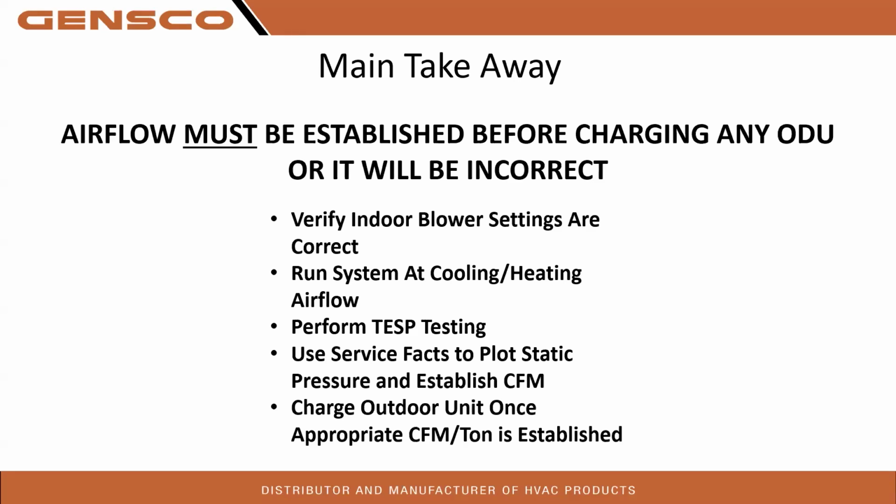Even if you use a true flow plate, that is great. Still need that information, right? A true flow plate does not give you an excuse not to do static pressure. We have to do that. And obviously, charge the outdoor unit once all the airflow is set. And we are charging at 400 CFM per ton. So let's really keep that in mind.